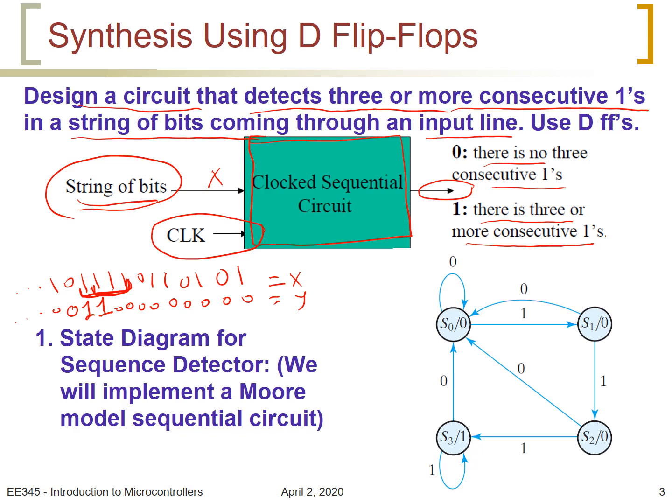We said the first step is to find the state diagram for what we call the sequence detector. And for the state diagram here, we start as follows. We assume we are in an initial state that is called S0, and its output is 0. S0 is the initial state, which means we will start looking at the sequence, and it means that we have no ones yet, or we can say that we have 0 ones so far. If we receive a 0 while we are in S0, we remain in S0 because no ones were received. However, if we receive 1, we must go to a different state that we call S1. Its output is 0, and S1 means that we have 1 already received.